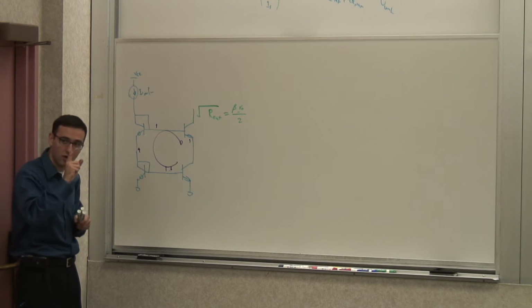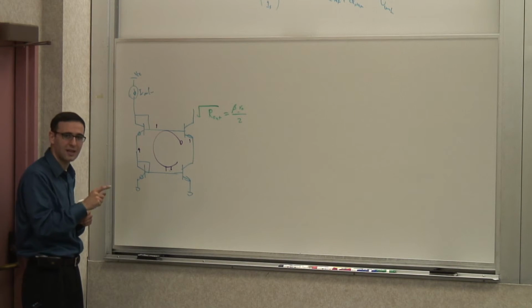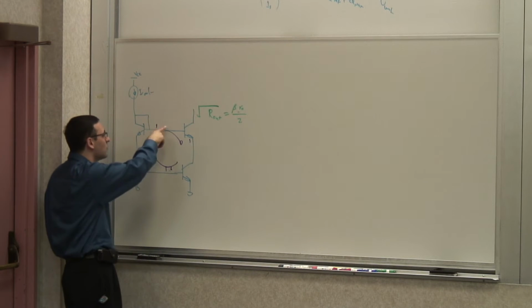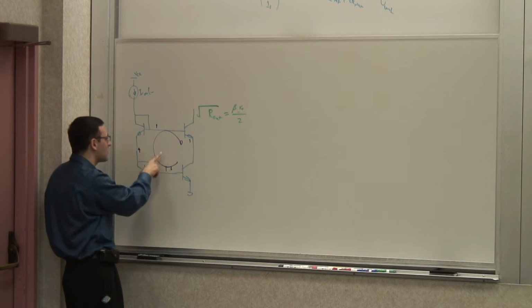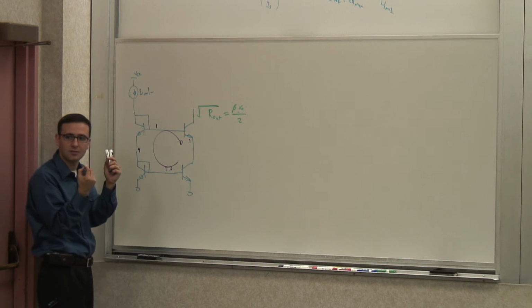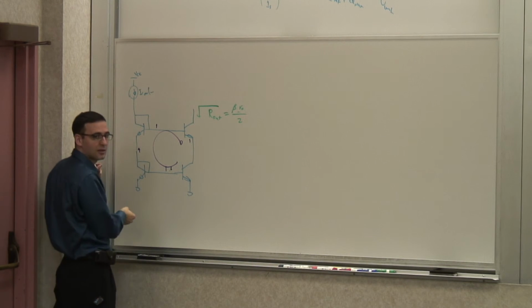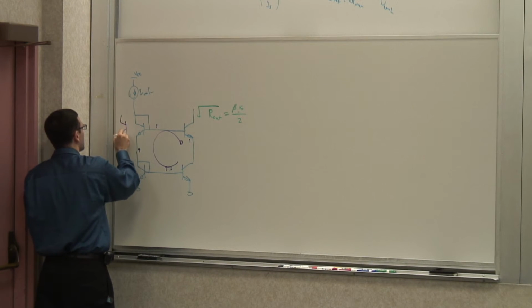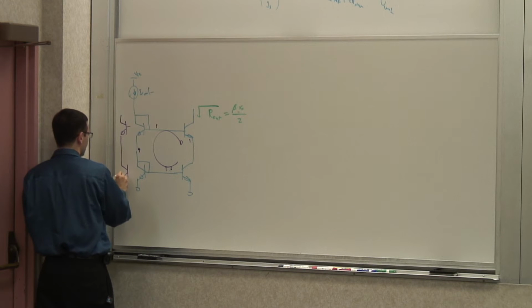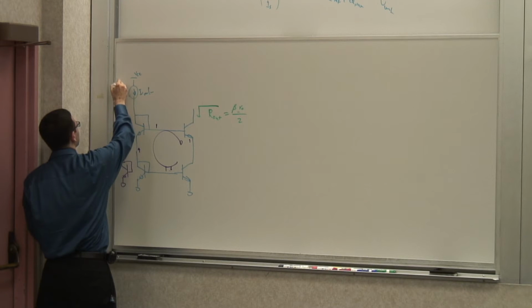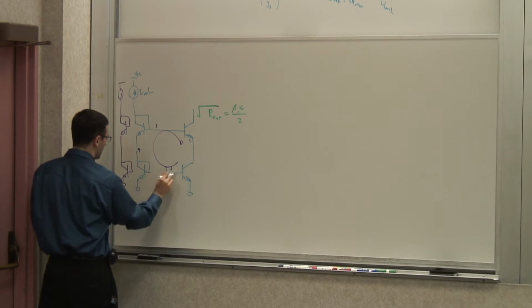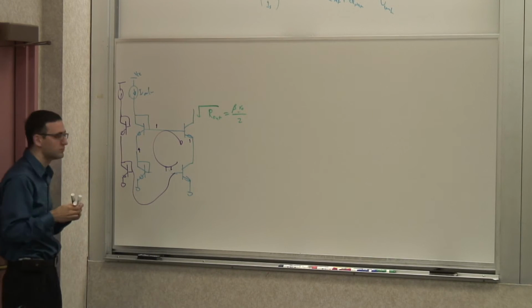Now, if I were to get the beta RO, exact beta RO, there's a way to do that, but nobody ever does that. Let me show you how. You want to get rid of this path, so you want to generate these two voltages as two independent voltages. Problem is that these are not exactly independent, right? They're coupled to each other. So what you can do, you can make an alternative branch here with diode connected transistors and another IREF. Okay? And connect one of these to this branch and use this one to bias this branch.